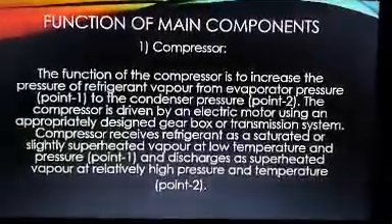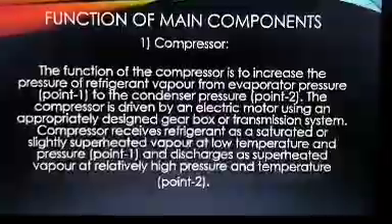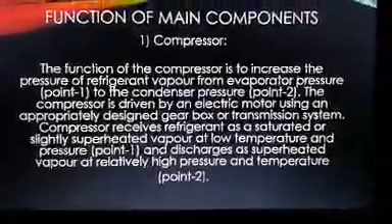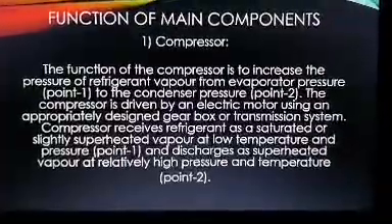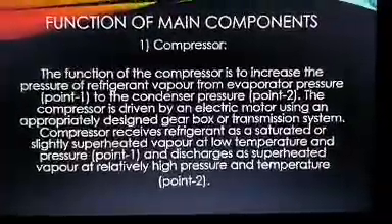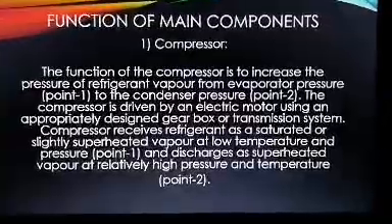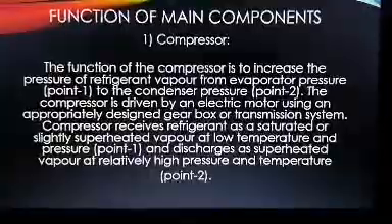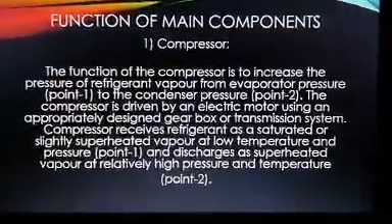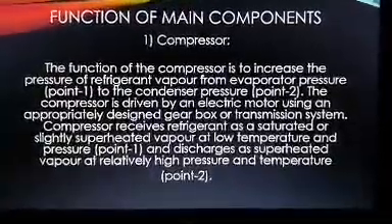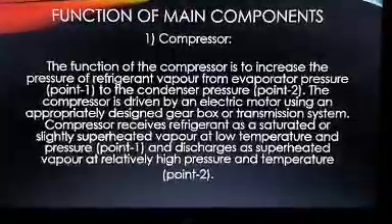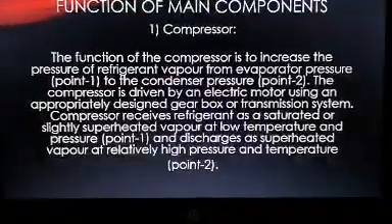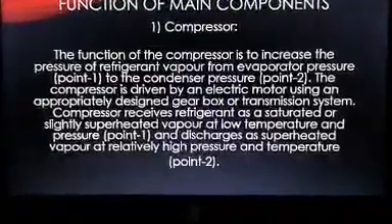The function of the compressor is to increase the pressure of refrigerant vapor from evaporator pressure, 0.1, to the condenser pressure, 0.2. The compressor is driven by an electric motor using an appropriately designed gearbox or transmission system. Compressor receives refrigerant as a saturated or slightly superheated vapor at low temperature and pressure, 0.1, and discharges it as superheated vapor at relatively high pressure and temperature.